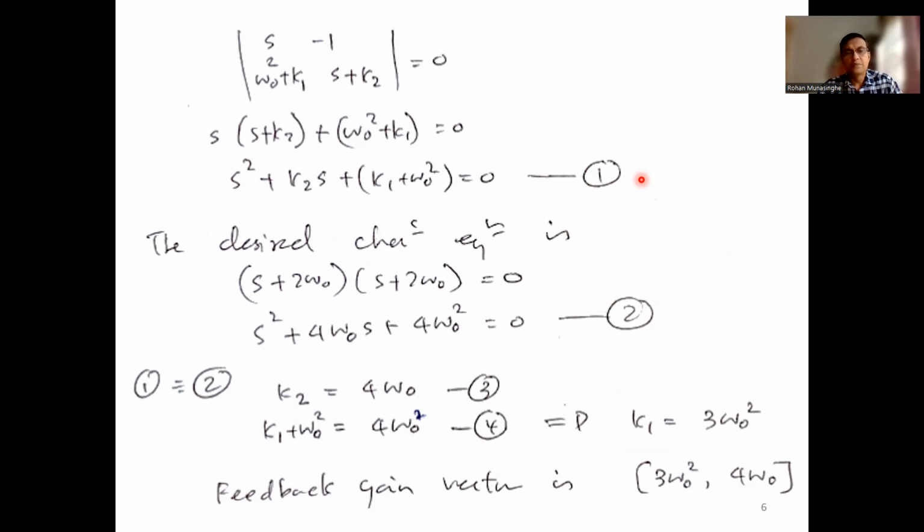With state feedback. You can see K1, K2, we have two gains because we have two state variables, theta and theta dot. And we have two gains, right? K1, K2. So when you measure theta 1, you multiply with K1. When you measure theta 2, you multiply with K2. Right? Then add them together and put a negative sign, feedback.